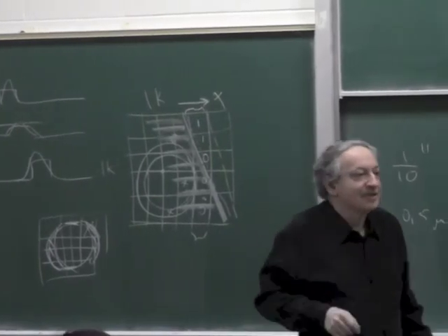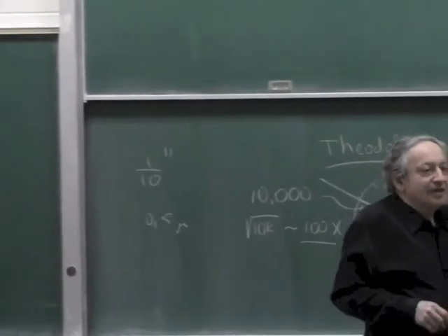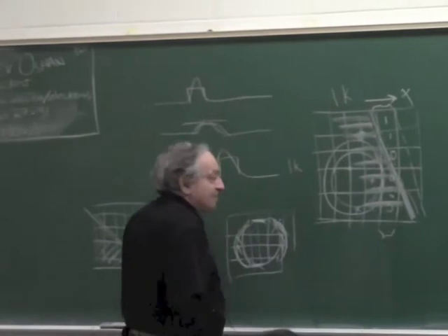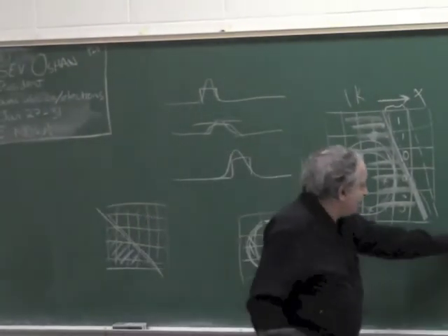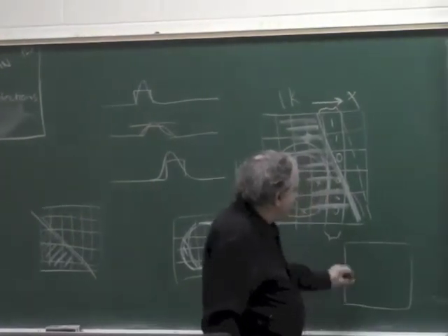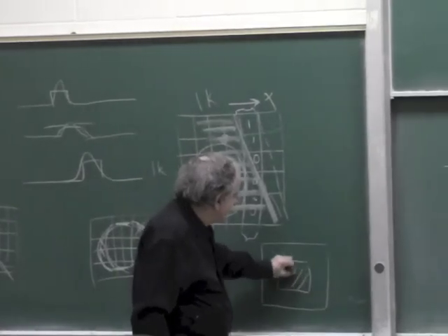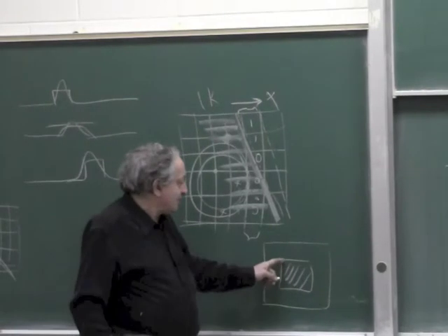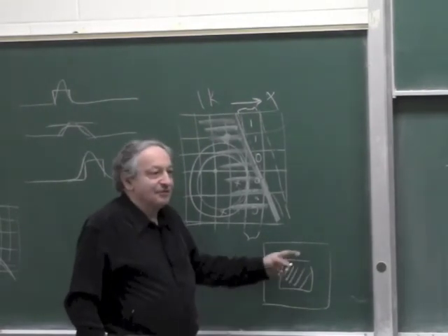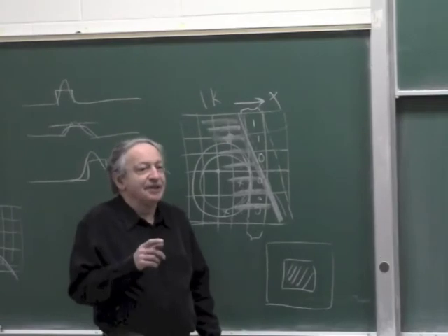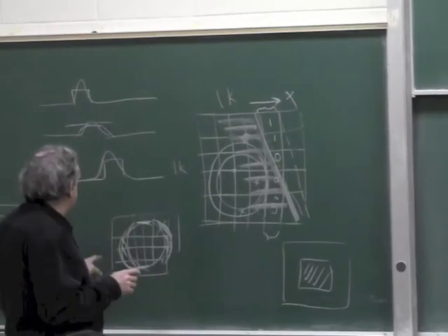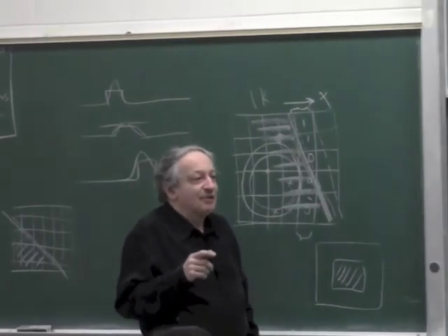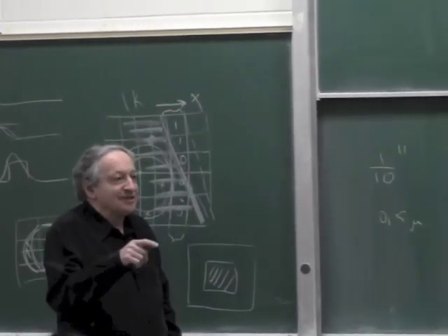Okay? Yes, please. Well, what about rotational movement? There's no problem to do it. You just need a target which is not rotationally symmetric. Because imagine if you had a camera and you projected a square. Of course, you can analyze how much this end moves, how much this end moves, and you'll have rotation. And you realize right away that you can tailor this pattern to what you want to move, to make the largest number of pixels change when the change you're interested in occurs.